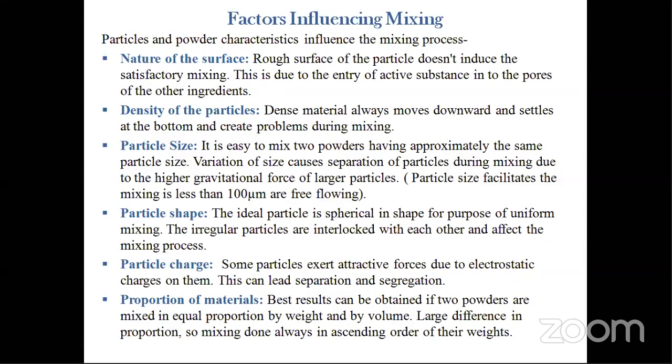Next is the density of the particles. Density of the particles means when your powder contains some amount of water or other particles, the density or weight of the particle increases. So when your material becomes dense, what happens? It goes to the downward portion, or the floor, of the mixing equipment and settles down there. So during mixing, if your particles settle in the downward portions, what happens?